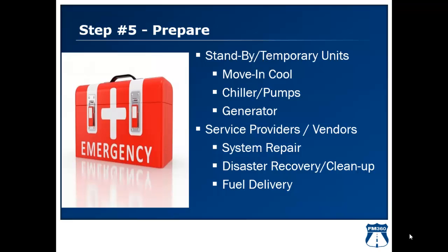What about fuel delivery? When Hurricane Sandy hit, that was actually one of their challenges as well, was they couldn't get enough fuel to keep the generators running in New York City. They were having to bring fuel trucks from the Midwest and further to supply those generators to keep those emergency systems operating. What do you have in place? Do you have 2 fuel providers identified? Do you have them contracted and their contact information and so forth? Again, all things that need to work into your procedures and into your escalation and communication protocols.